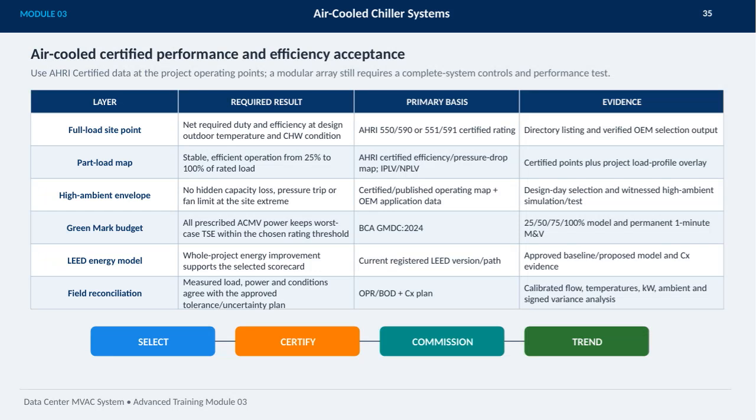This slide covers the critical aspects of air-cooled chiller system certification and performance acceptance in data center MVAC systems. The foundation here is using AHRI-certified data at the exact project operating points to ensure accuracy. Even in modular arrays, a comprehensive system controls and performance test is essential.